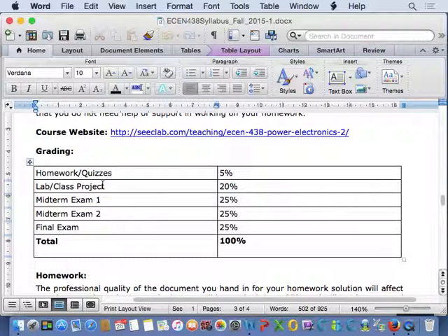Some of them are actually online all the time. Some UPS systems are for very critical uses, like if you're a heart patient on life support. You cannot afford for the system to fail, right? So typically that kind of UPS is online all the time. Even when there is power coming from the grid, it's passed through the UPS to make sure that it's there. And if it's not, the UPS jumps in automatically. There's no mechanical transfer switch and then a generator starting up. A generator will start up in the hospital later.